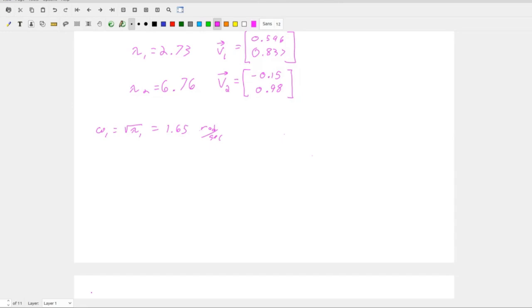Inverse square. So we do that when we have a mass normal, when we solve the eigenvalues with the mass normalized stiffness matrix. But here we solve them with a generalized eigenvalue problem. So our eigenvectors are our mode shapes, but they just have to be scaled. Does that make sense? So we're going to have, again, this is where it gets a little confusing.